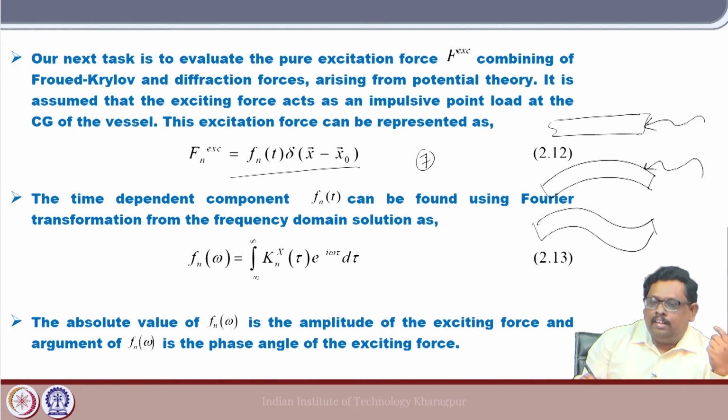At that time, do I consider that this is the fundamental structure and it will stand still, and then I hit the wave here and try to figure out the pressure distribution along the hull, and then from this pressure distribution I can get the exciting force.